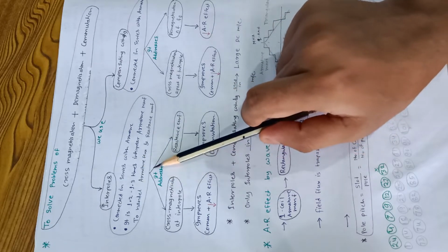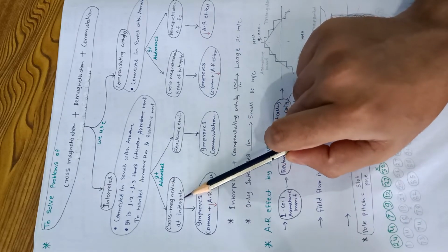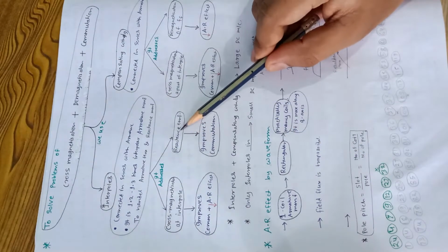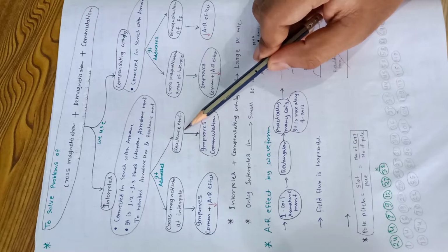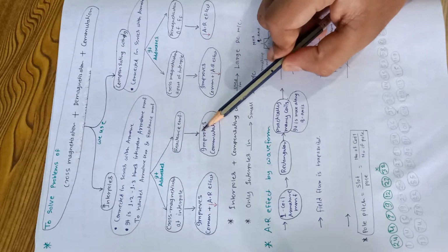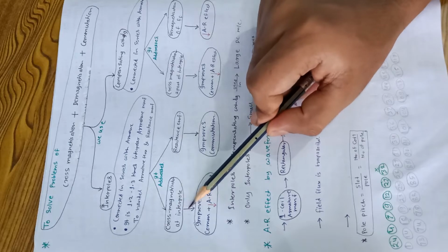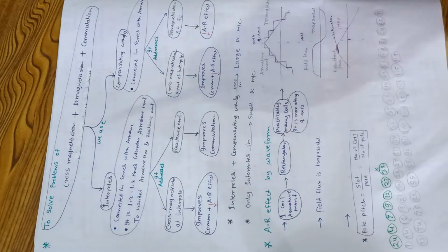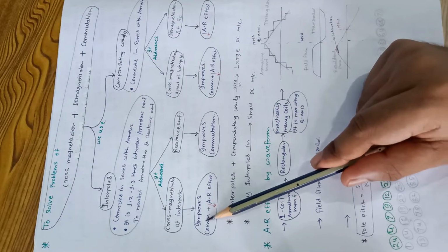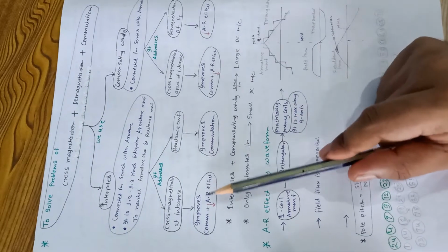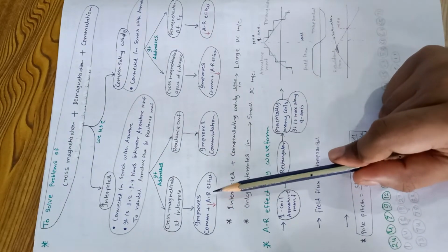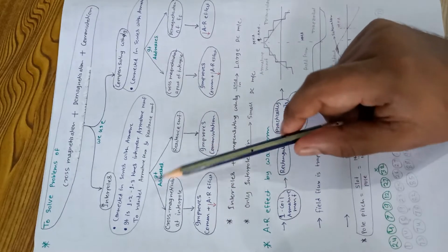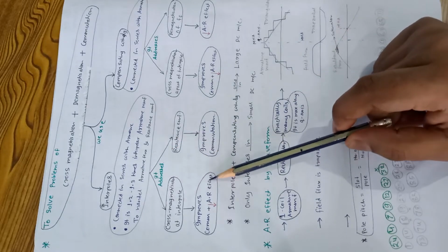In that way it will address cross magnetization at the interpole and reactance EMF. If we reduce reactance EMF, then it will improve commutation. If we address cross magnetization at the interpole, it will improve commutation and also reduce the armature effect. So overall, the maximum advantage we get from the interpole is that we improve commutation.